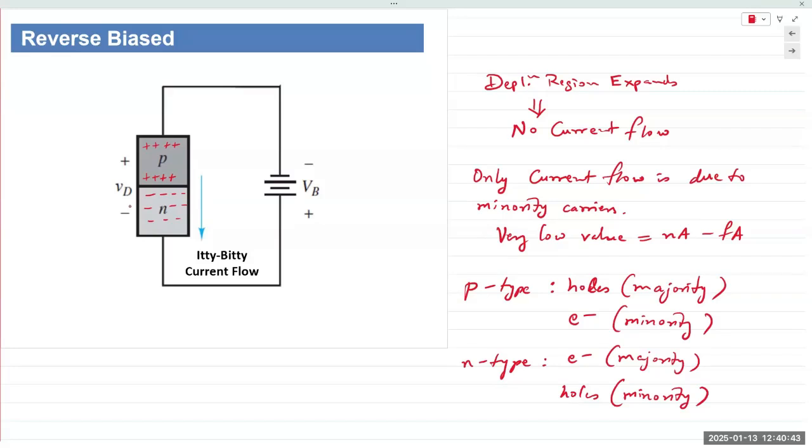So the current flow that takes place in a p-n junction diode can take place due to both the flow of electrons as well as the flow of holes. Polar opposite charges, positive and negative, but both of them are crossing over at the same time. And the same effect also occurs in transistors, specifically the bipolar junction transistor. And because the flow of current takes place due to two separate charge carriers, these are also known as bipolar devices.